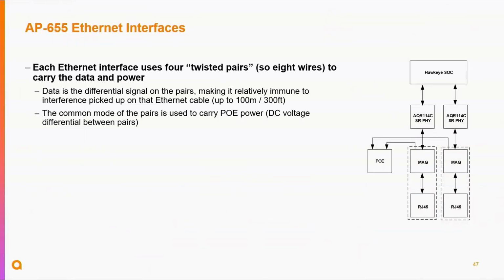Main internal functional blocks. Ethernet is actually pretty straightforward. When you plug in the cable, the first thing that signal sees is some magnetics, a transformer. In our case, those magnetics are part of the jack on the board. There's a little metal piece that has not just the connector but also a transformer built into it already. That's called a mag jack, I believe. On the other side of that, we buy our components from Aquantia. They convert the analog signals from your Ethernet port into a digital signal that then interfaces with the system on a chip component.